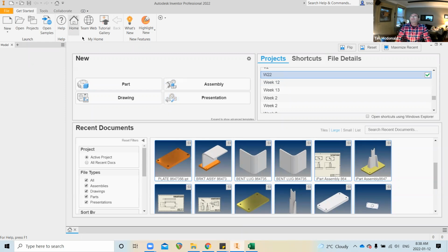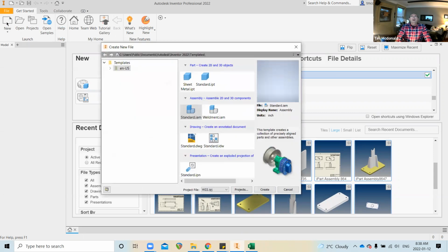And there'll be a couple of parts that you don't have to convert. It's almost like you're adding on a separate identity for a component by creating it as an iPart. But first of all, you have to create the component. So I'm going to click on the new tab. And I think the first component I'm going to create will be a sheet metal component.